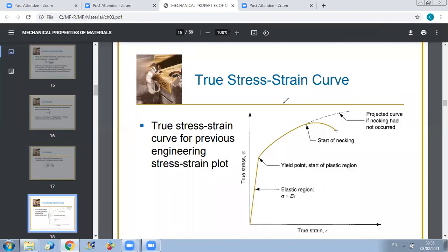And if I give you the following graph, I have first an elastic region, and then for the other part, let's say it's like this. So here it's a little bit flat. It's not easy to determine really where is the maximum. So it will not be simple to determine at which point we'll have start of necking. This is why the true stress, true strain will be much of help.